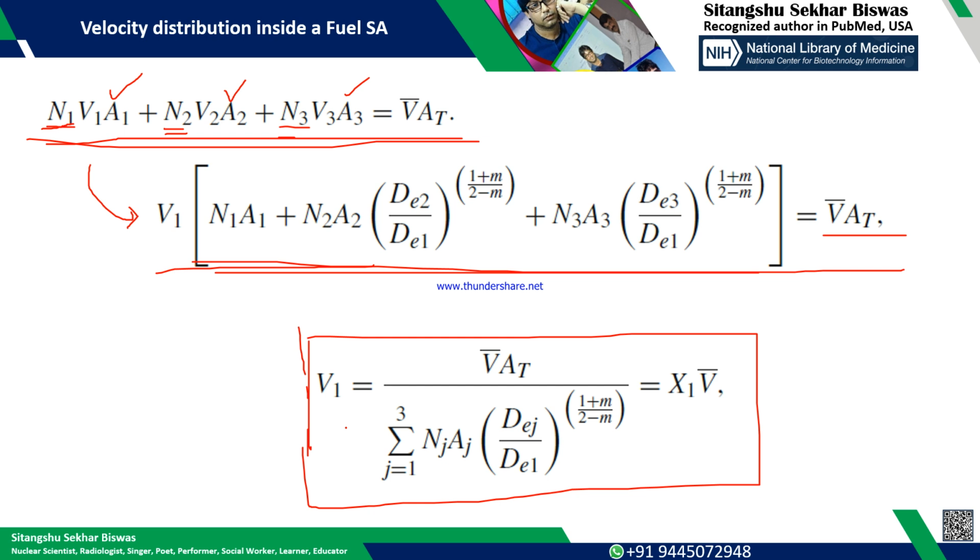With that we can find out. So as I told, the exact figures, how much velocity and all, I can't remember, but we considered it as turbulent flow in a smooth tube. So we took the value of m as 0.25. With that we validated, and our COMSOL model was also benchmarked with that small experiment.